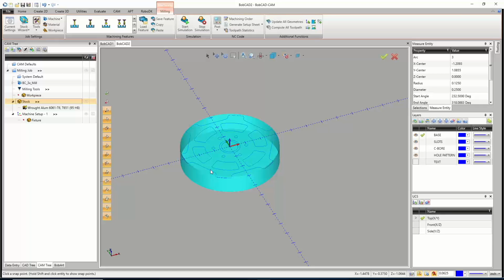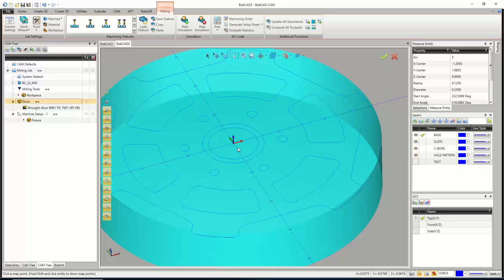And then when he runs his face pass, wherever that tool's at is where it runs and makes the top. And then when he flips the part over and gets it all measured, he then knows how much he's got left. So with that same face pass, he'll just drop Z, set 0, run the pass, and then adjust from there to get the perfect thickness. So he doesn't even add extra material in his stock wizard because he's going off the rough stock, and with his face pass, he's creating 0. So he never has to deal with tool paths with negative.